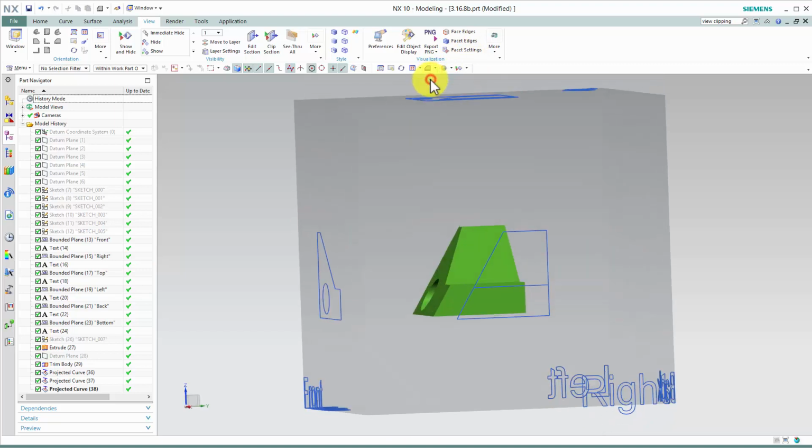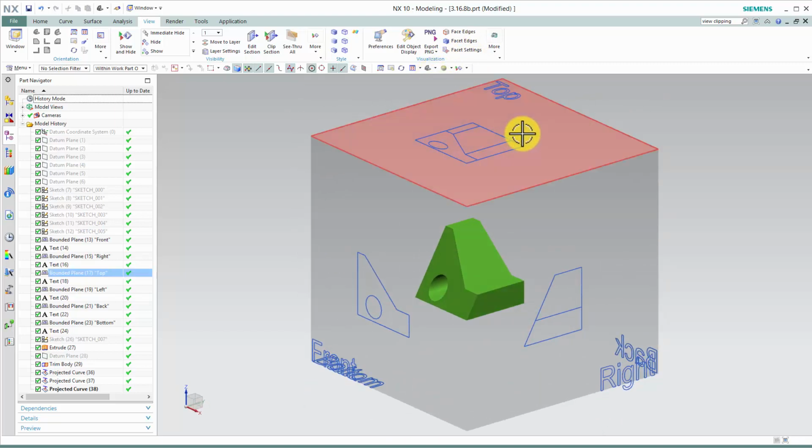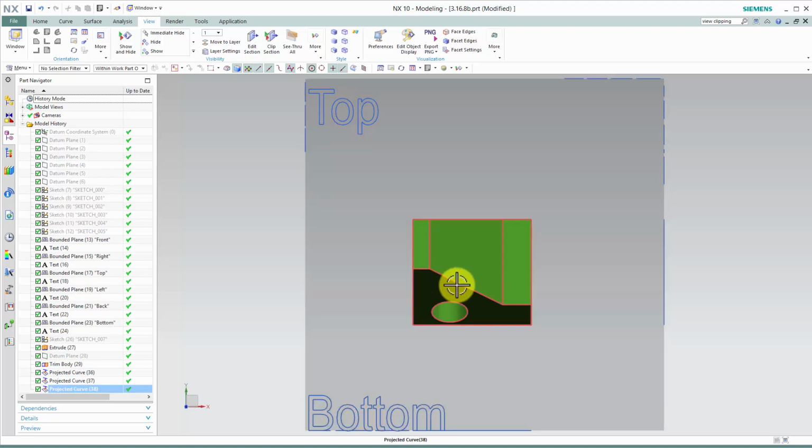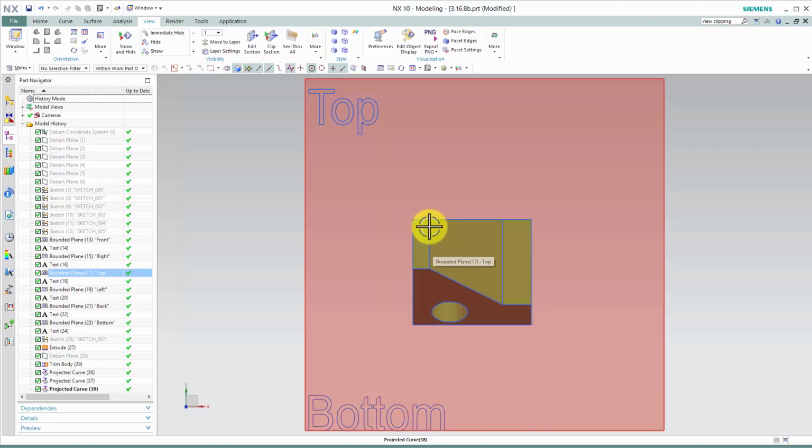And finally, let's verify what the top view would look like. The top view is really pretty interesting and quite a bit more involved. And notice again, we have four lines that represent the outside perimeter. We have a line that represents an elliptical circle, that represents the opening, the hole. And then we have all of these other interior lines that represent the hard edges or the hard lines between various faces that are seen from the top orthographic view.